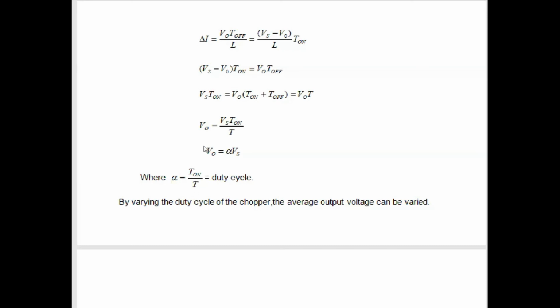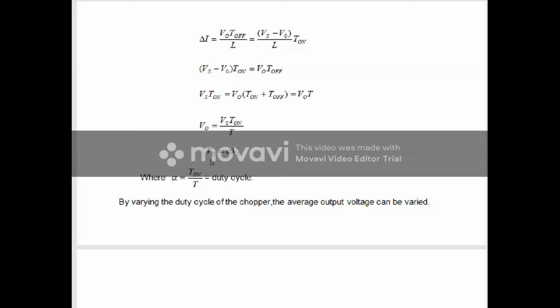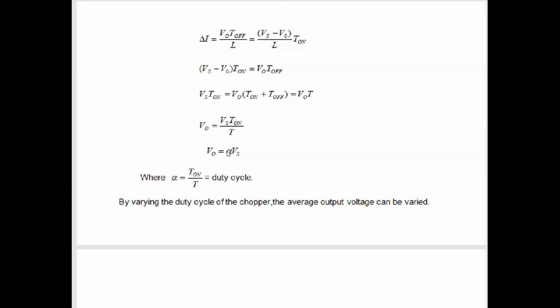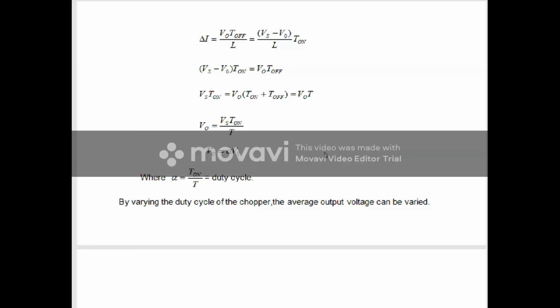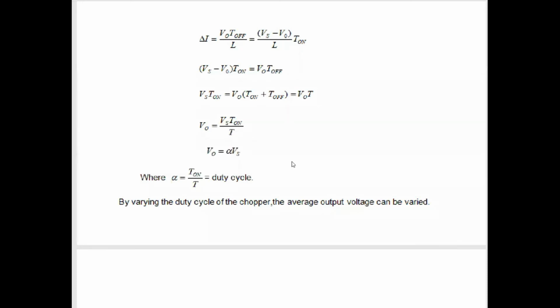Okay, apart from this equation we can say that the output voltage of this buck converter is always less than the input voltage. Correct? அப்ப if you are applying input voltage 5 volt அப்படினா நமக்கு வந்து alpha வந்து 0.5 ஆ இருக்கும்போது what about the output voltage? We will get half, that is 2.5 volt. Correct? அப்ப நம்ம input 5 volt கொடுக்கிறோம், we will get the output is 2.5 volt. So that's why this converter is called as the step down converter. Okay, இதான் derivation. இதே மாதிரி தான் நம்ம அடுத்த 32க்குமே பண்ண போறோம். Okay, it is easy one.